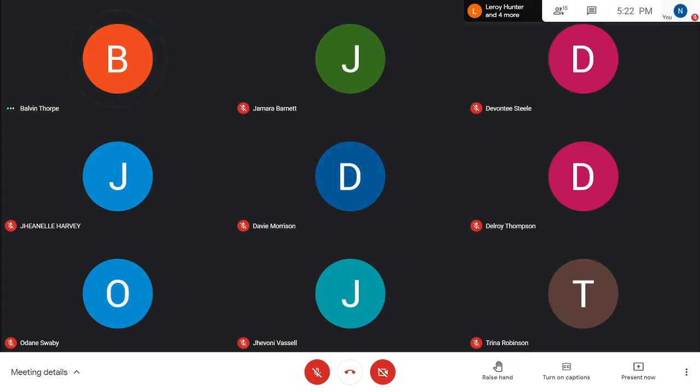So it means that you're applying an input current, the amplifier amplifies it, and outputs the amplified current. That output amplified current is fed back through a resistor, which means that across that resistor you can actually get an output voltage. You follow me? Yes, sir. Good. And therefore, that specific circuit can be used as a current to voltage converter.